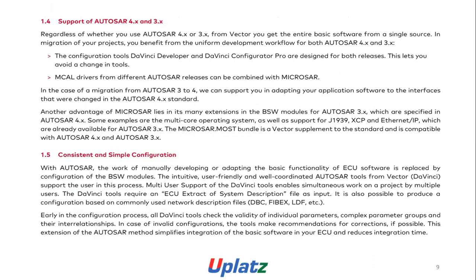Support of AUTOSAR 4.x and 3.x: regardless of whether you use AUTOSAR 4.x or 3.x, you get the entire basic software from a single source. In migration of your project, you benefit from a uniform development workflow for both AUTOSAR 4.x and 3.x. The configuration tools DaVinci Developer and DaVinci Configurator Pro are designed for both releases. This lets you avoid a change in tools. MCAL drivers from a different AUTOSAR release can be combined with Microsar.